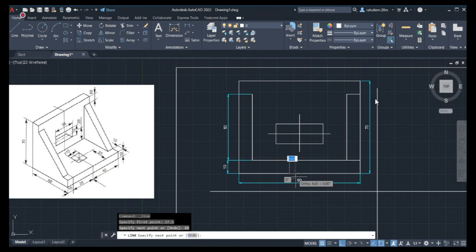Okay. Then once again, I'm going to trace from this point forward. The width of that square is 50. And then once again down 10. This is where the square is, but it's hidden. Now, how do I indicate? Let's indicate those things first. So these are hidden lines. I cannot see that there is a square hole there. What do I do?